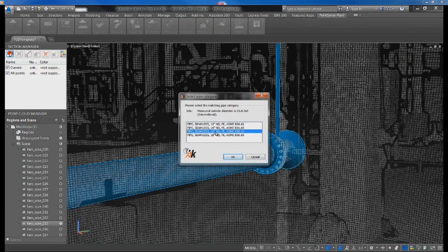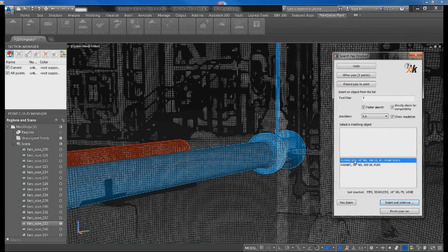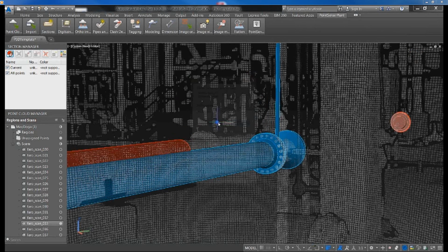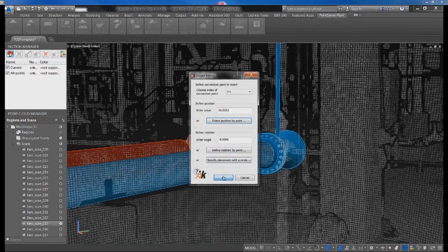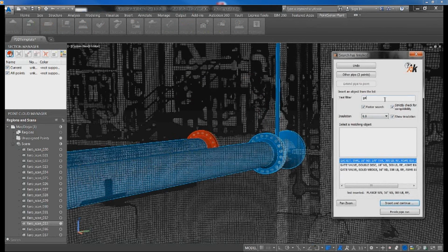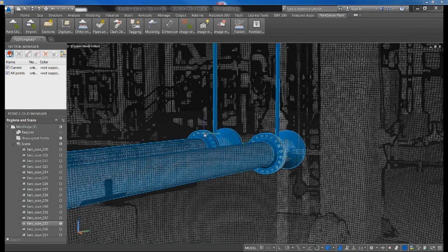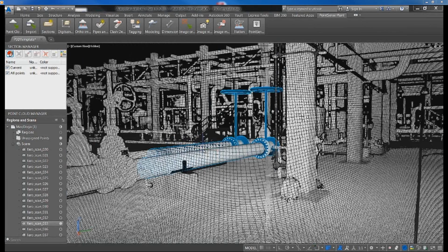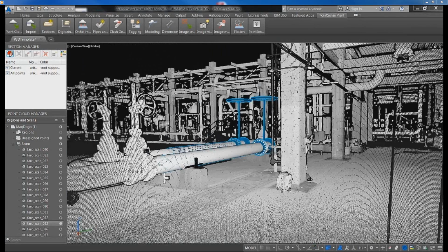And then all I need to do here on this next pipe is the exact same thing. 2 points on the pipe, don't worry about the weld, toggle my insertion method for the flange, and then any point in the back of face. I always tell people if you're looking for that right flange insertion, you're doing good if you can see every single bolt in the cloud data. So those are those 2 lines, not to mention the line that we did before that.